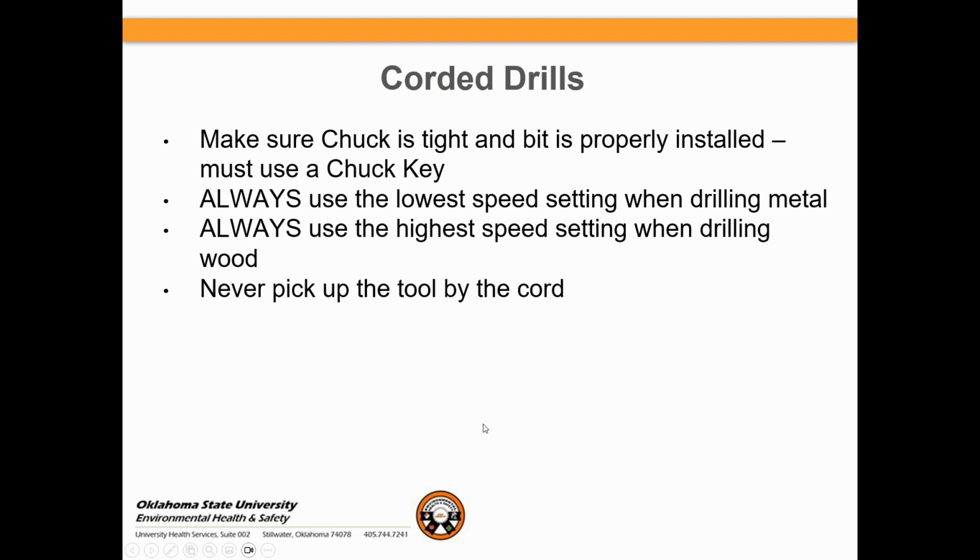Let's go to the next one as far as the corded drill. Make sure the chuck is tight and the bit is properly installed. Must use a chuck key. Always use the lowest speed setting when drilling metal. Always use a high speed when drilling wood. And never pick up the tool by the cord.